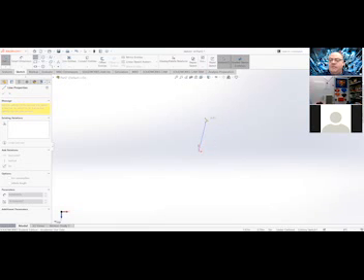Now in AutoCAD, I'd have you press F8 to keep your line straight. But if you bring your line going up, notice there's a yellow box now with a black line in it. That means that this line is perfectly vertical, and we're good to draw there. We don't have to worry about an F8 key to make it lock down. And notice it's also giving us the length of the line and a comma and its angle.